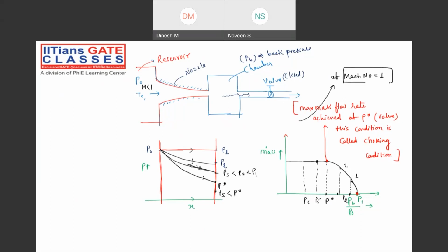When the Mach number reaches the value 1, there itself we are getting the maximum mass flow rate, right? When the velocity of the fluid becomes sonic speed, that is the speed of sound, whatever the mass flow rate through the nozzle will be at the peak value, the maximum value you will ever get from the nozzle, right? Understanding my point?